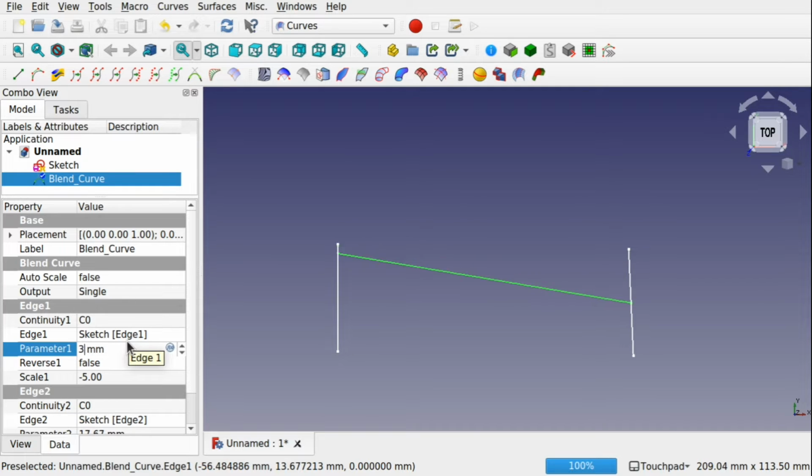Let's change this to 35. You can see it's gone all the way down to the bottom. And if I do it to something like 40 and hit enter, we've got 35.25, which represents the height of that edge there, that sketch. So you can see how this relates to the height of the sketch and what placement along that edge that will be placed. So if I hit 0, it's going to place it at the top, and if I do something like 40, it's going to round it down to the height of that element and place it there.